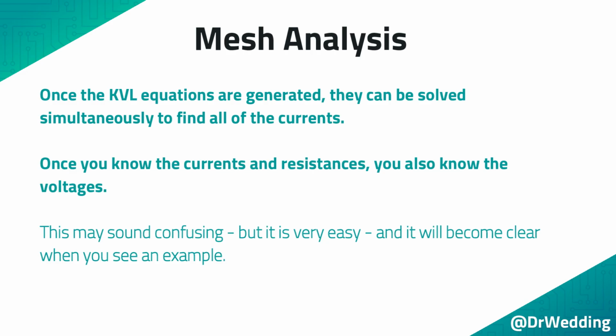Once the KVL equations are generated, they can be solved simultaneously to find all of the currents. Once you know the currents and resistances, you also know the voltages. This may sound confusing, but it is very easy, and it will become clear when you see an example.